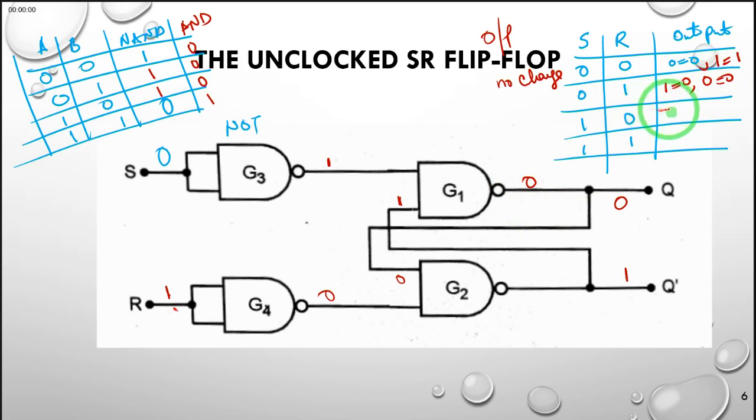For that reason, we say if it was 0, it will still become a 0. Therefore, we are saying that when we have set S to be 0 and R to be 1, the output will be a 0. So we can now consider when S is 1 and R is 0. And we can start with the previous state being a 0.